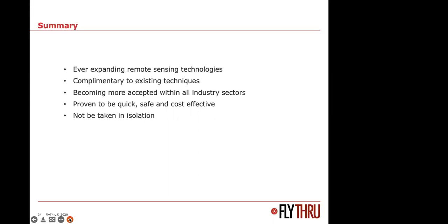And we're looking at how we automate that process by putting a sonic system onto a drone and a hammer, which is a little tap tester, to be able to record the sound waves, and eventually automate a flight plan with a drone pushing against a structure and making a small tap test to record that type of data. So it's amazing the type of things that are being done.